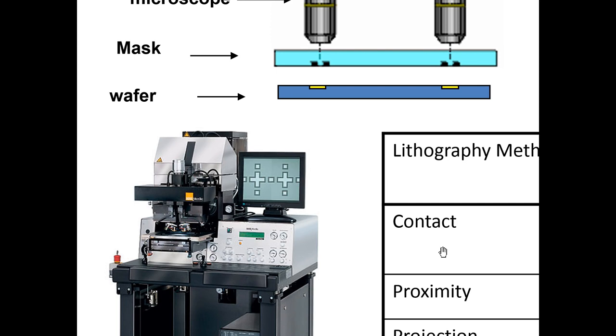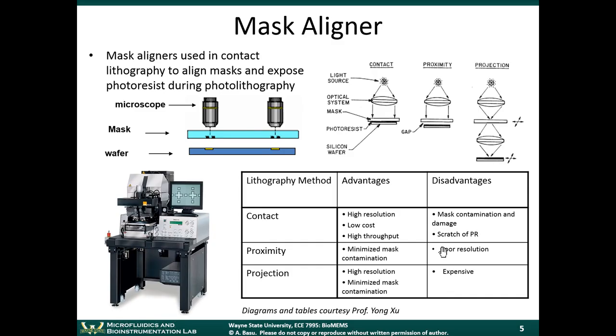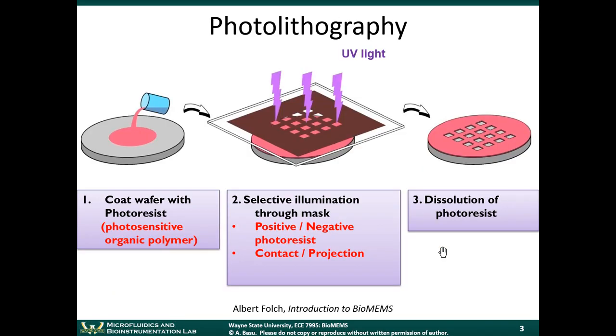Okay. Now when we're talking about layers, keep in mind that this type of photolithography process is done repeatedly. What we're doing is we are building an object layer by layer. In one plane, we're defining what it looks like on a 2-dimensional plane, and then we define the next plane on top of that. So we can make complex objects by having multiple steps of deposition and then photolithography. So we'll get to that later.